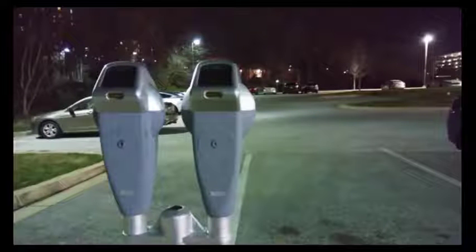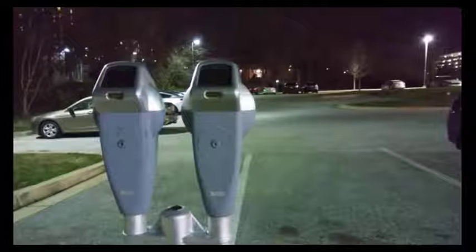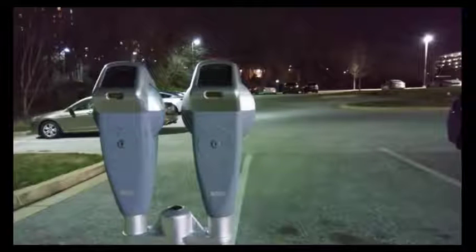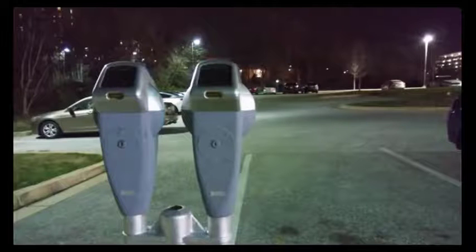While out mapping, there were a couple of environmental things that I noticed that I was worried may impact the quality of the data that I was taking with my LiDAR. For instance, in this image, there are clearly many streetlights in the parking lot that created a significant amount of noise in the image. In addition, surprisingly, the brake lights of the cars behind the parking meter were being picked up in the Python code and plotted as points in the point cloud.